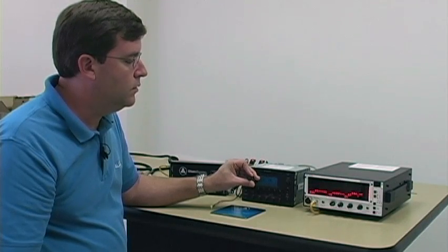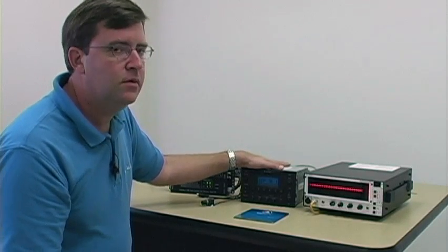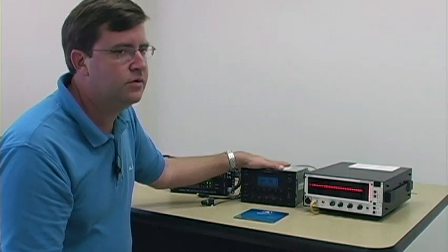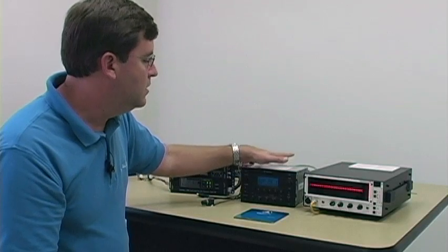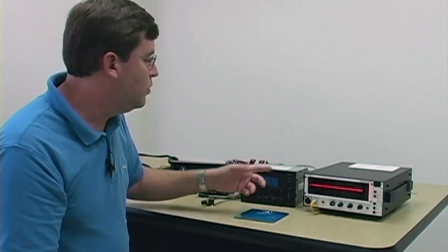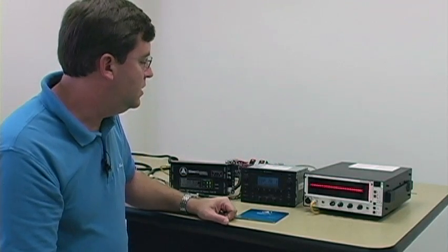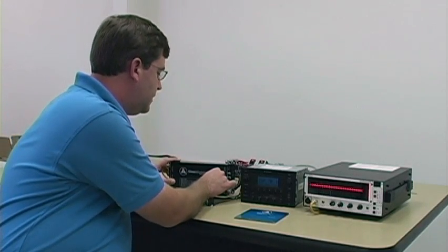for good aftermarket results. Whenever you're dealing with a head unit that has full range outputs, the implementation is very straightforward and very simple, like in this case with this Volkswagen head unit. This unit simply spits out 4 equalized full range signals. It's important to note also that the signals coming out of this radio are different in the front and in the rear. I'll give you an example.